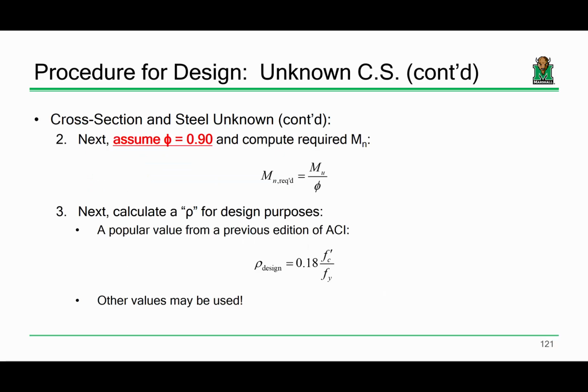Don't worry. All right. So when it's all said and done, you're going to have some dead loads on the beam. You're going to have some live loads on the beam. Some of those dead loads are going to come from the beam self-weight. And when it's all said and done, you're going to get an MU, a factored bending moment on the beam. On homework number 1, you should have had some experience doing that. Remember, what was the first problem? You had a floor plan, you had a dead load, a live load, you had to reduce that live load, tributary area, distribute it to a floor beam, WL squared over 8. Y'all remember that? So you all should have kind of an idea of how you would get an MU value,